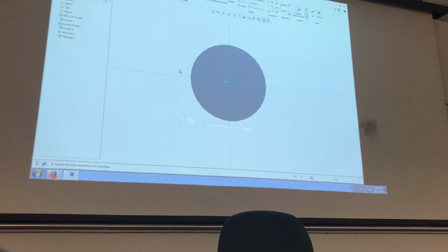You've used Inventor. Who's used AutoCAD? They use a lot of construction lines. They use the layers. You set one layer up for construction lines, right? Well, you can use construction lines here too. But instead of going into construction mode, we're just going to use this center line here, and we're going to use it as a construction line. Are construction lines where you can merge shapes into each other? Now the construction line actually sets up a line that you can snap to.